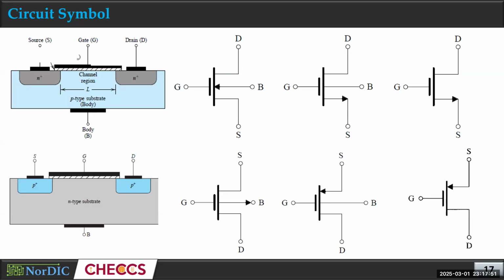So these are the symbols where, as I mentioned, you have 4 terminals: gate, drain, source, and body. And typically in NMOS and PMOS, the body terminal is connected with the source. That's why you can see that in the last column here, the body is not there, right? We only have gate, drain, source. That's the reason, because this body is actually connected to the source most of the time, you can say all the time. So if that's connected to this, then we can consider one terminal for both body and source. That's why we only see 3, right?